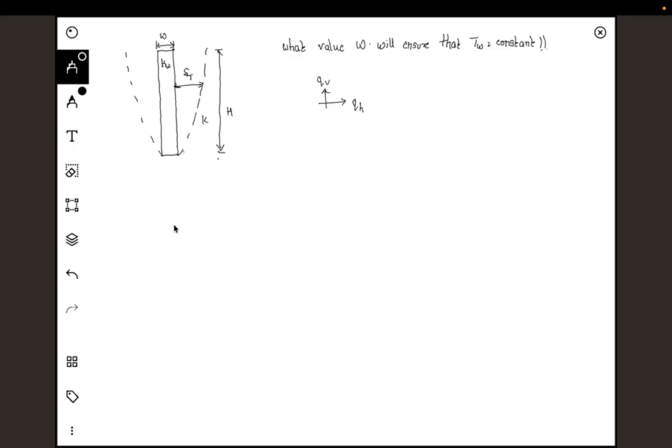And if, for example, the horizontal heat transfer is higher than the vertical heat transfer, or to put it in layman terms, the rate at which heat is going out horizontally is higher than the rate at which it's going vertically, then we can assume that the temperature here will not change much. There wouldn't be any temperature gradient, because if there is a temperature gradient, then the heat flux will have a finite value. Or put in other words, if the temperature is not constant, then there will be some heat flux going like this. So in order to make the temperature uniform, somehow heat has to move.